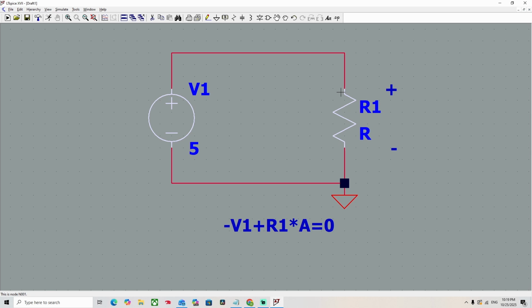So passive parts, such as resistors, certain capacitors, and inductors, anything that doesn't require an external power source to make it work, by default aren't polarized. Now I said some capacitors aren't polarized, so this would be an AC cap with no polarity symbol on one side or the other.